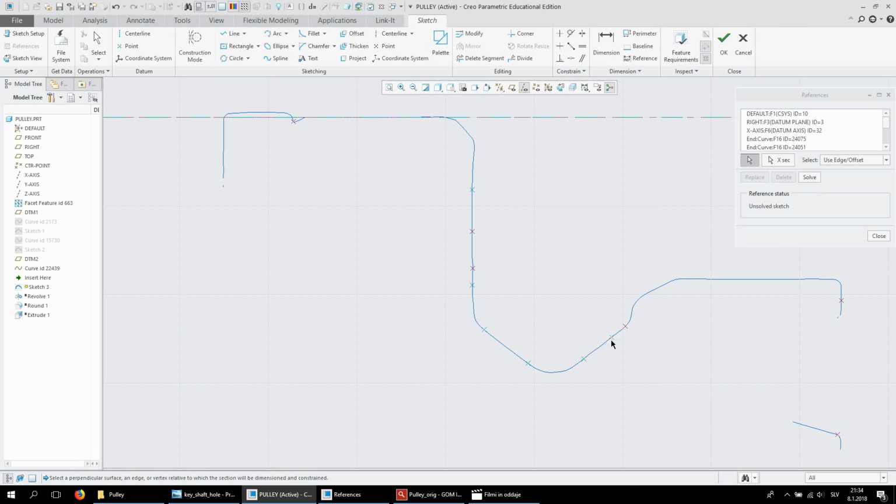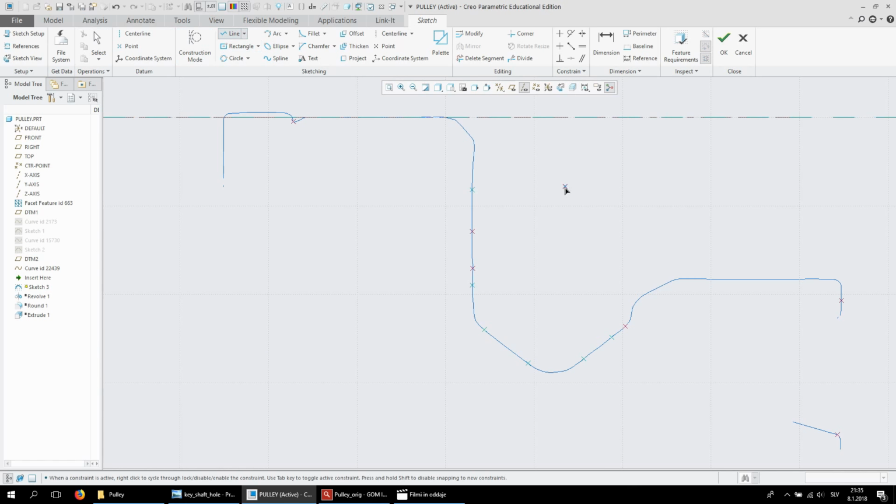So we're going to make a revolve with the center line here, but now I'm going to make both of these lines here just as a middle step. So I can close this and create lines here through this reference point.